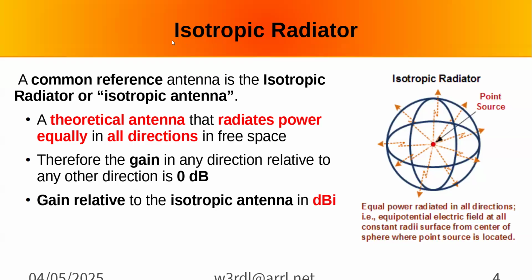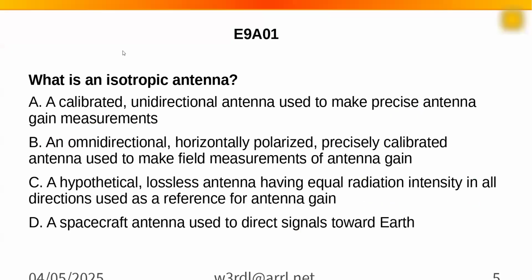So saying that your antenna has so many dBs of gain, in a direction. Yeah, in a particular direction. Right. Is that what you see as dB over isotropic? Yeah, it says dBi. dBi refers to dB relative to an isotropic. dBd is relative to a dipole.